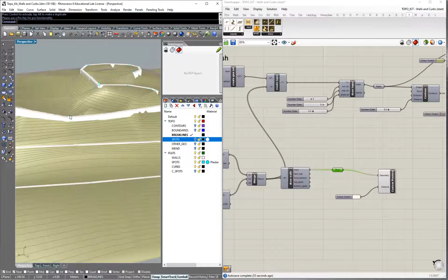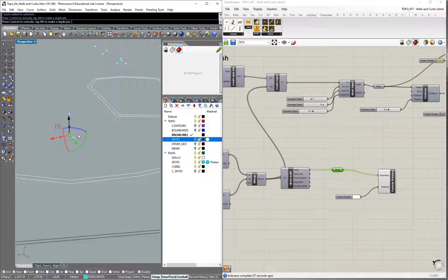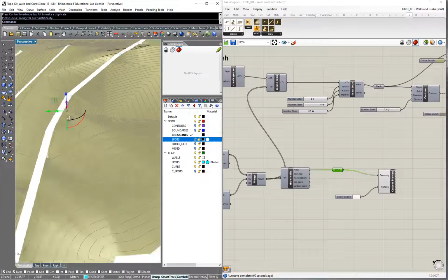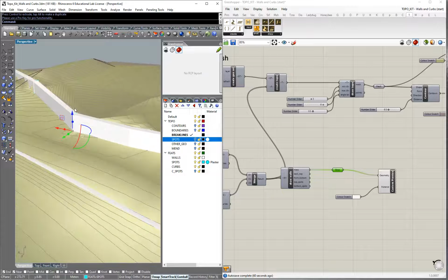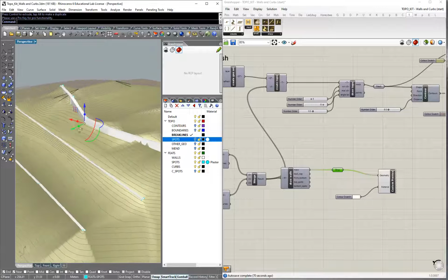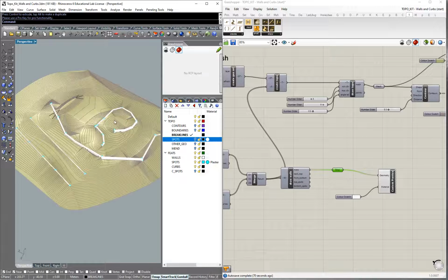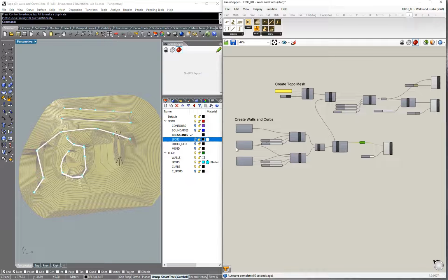Okay, so this is where this point will make a significant impact in the topography because it will modify. And so here I'm creating a sort of dam. So it's very important that because these points are used to create a new Delaunay mesh. So that's how it is create topo with features and how you can use these features to modify, including the boundaries and break lines, but also features such as walls, spots, and curves.